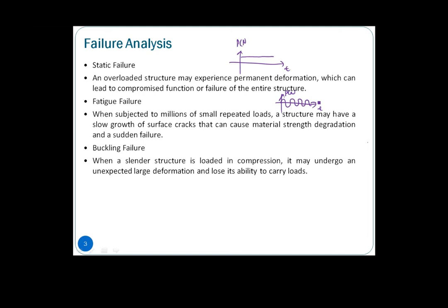Okay, it could be over time, depending on how high your loads are. So it depends on the number of cycles. It could be 10,000, it could be 5,000. If you have a very high load giving high stress, then probably 500 cycles it could fail. So it all depends on the number of cycles. It will create some weaknesses, for example cracks, onto your structure, causing degeneration of the strength of the material.